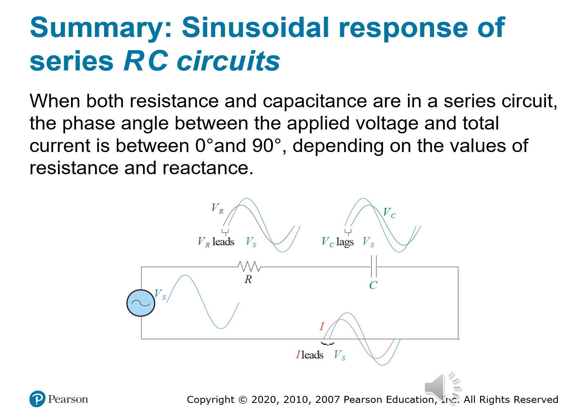If the resistor dominates, you have a small phase shift. If the capacitor dominates, phase shift approaches 90 degrees. And it's like tuning the dial on a frequency sensitive dimmer switch.